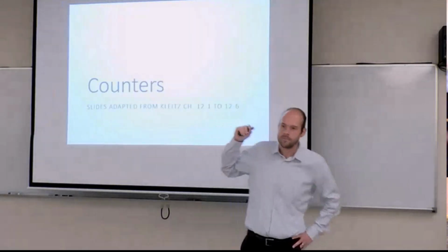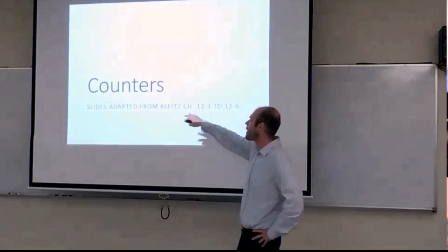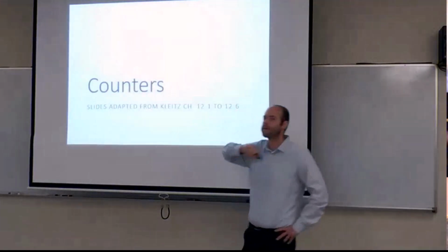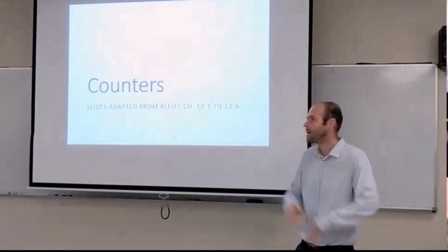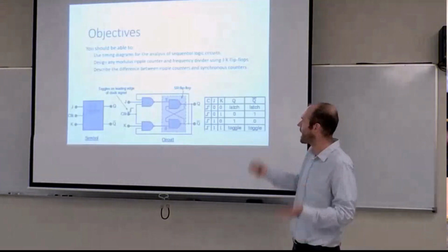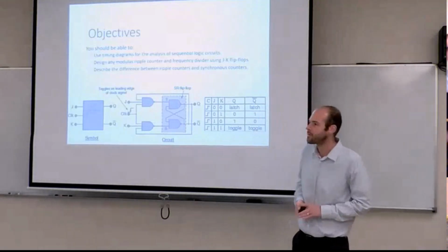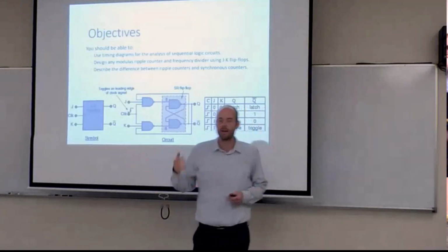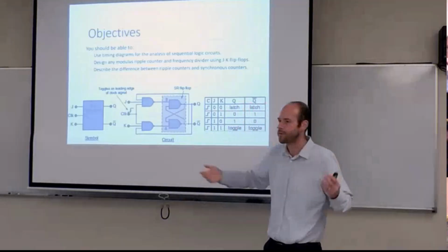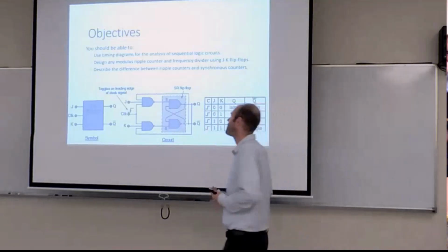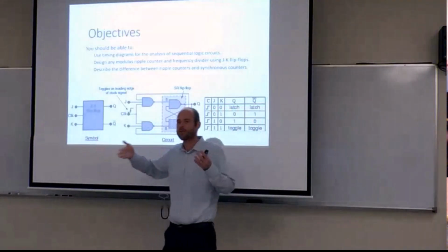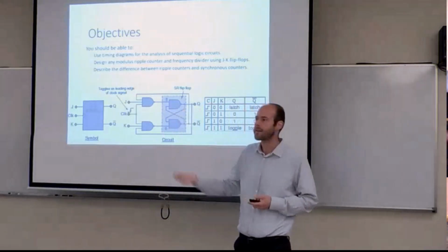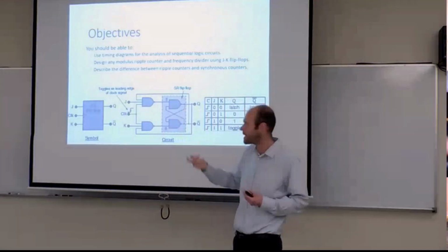So here we go. If you're following along in the book, which you have the complete book online, this is chapter 12, content we're diving into. The big picture idea is we're talking about counters. You definitely recall from last time we went through a sequence of building blocks. I started by just drawing 2 inverters on the board and looping it back on itself to retain a bit. We built out that structure in a few different stages through the SR flip-flop, set and reset flip-flop, which would just retain a Q bit.